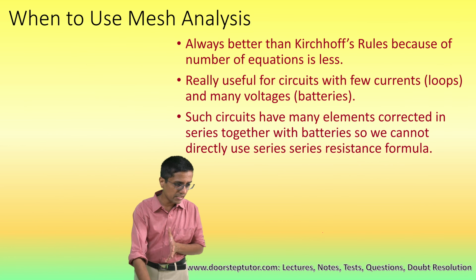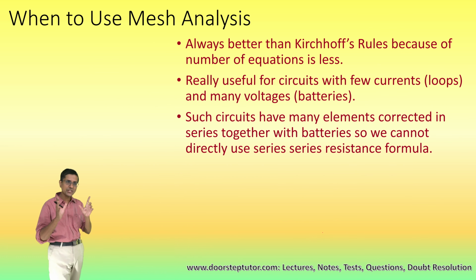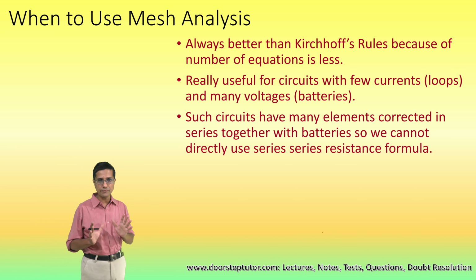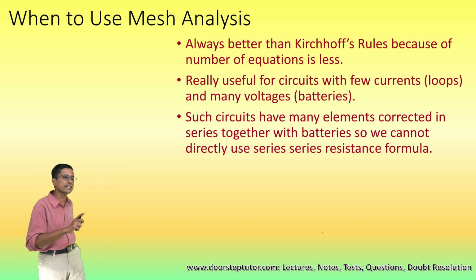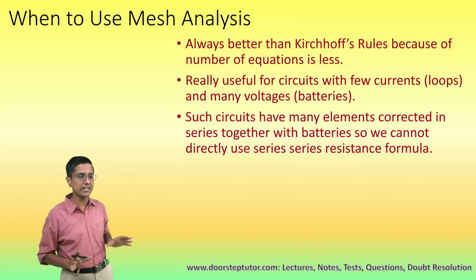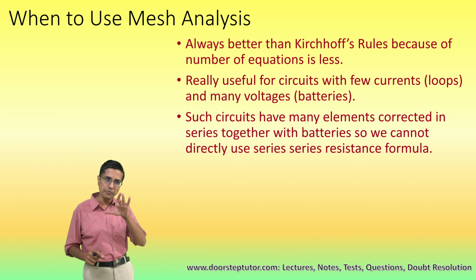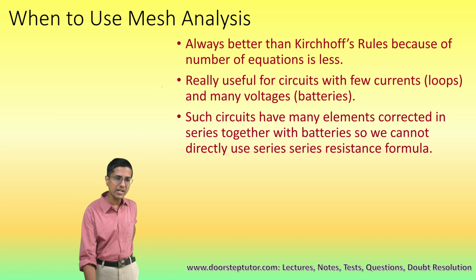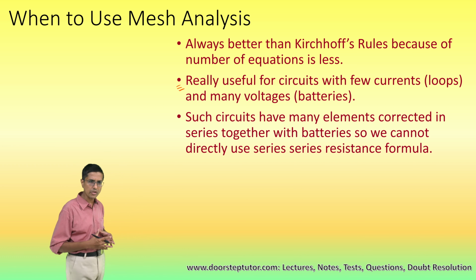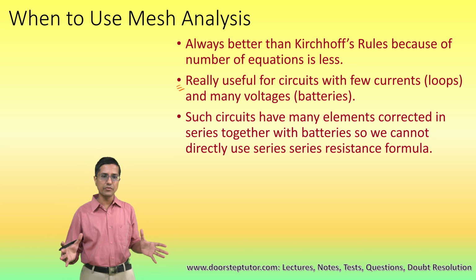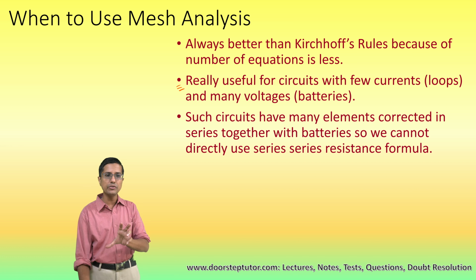So with this we conclude this section, but the main thing to take away here is this: the mesh analysis is always better than just blindly applying the Kirchhoff rules. Why? Because the number of equations would at least be one less than what you would have arrived with the Kirchhoff rules. So directly applying the Kirchhoff voltage and current law would give you more equations always. So we will use the mesh analysis. Now the mesh analysis really shines where we have only a few loops, and there are multiple voltage drops. So where we have only a few currents, we will use the mesh analysis.